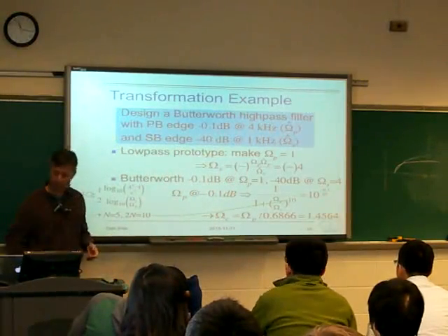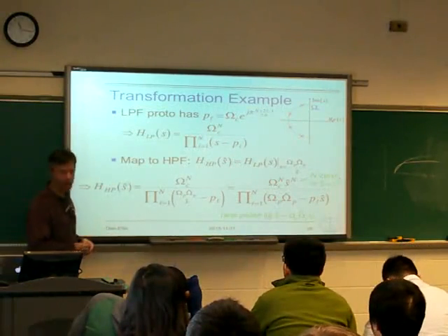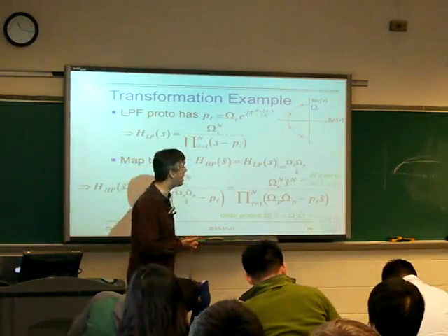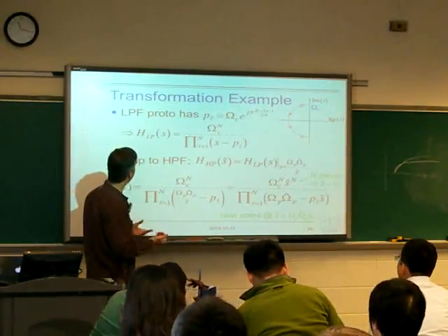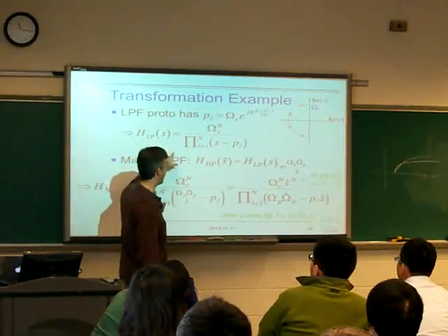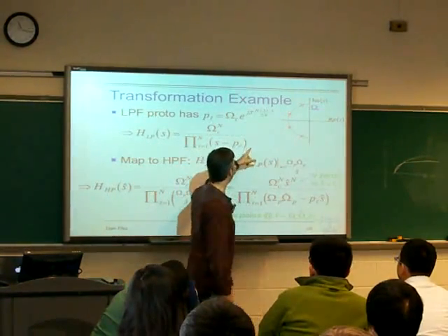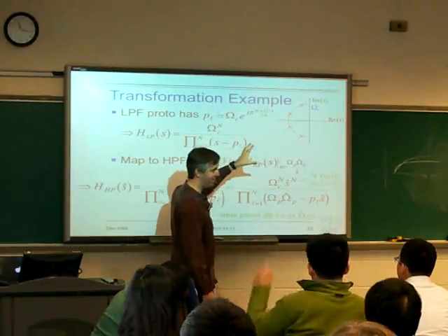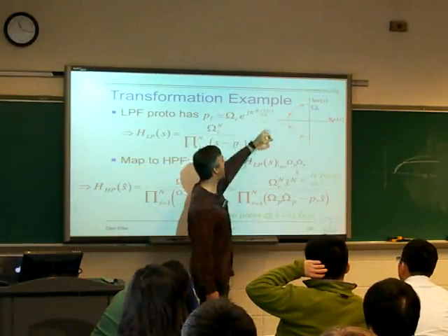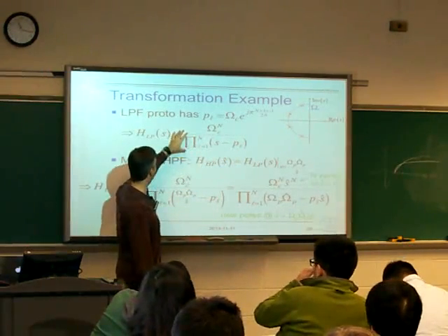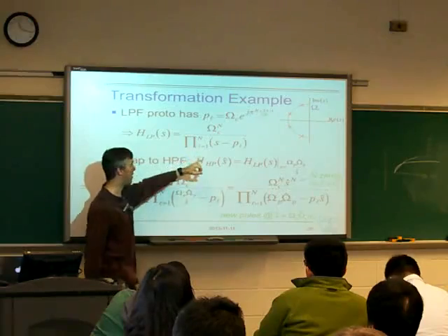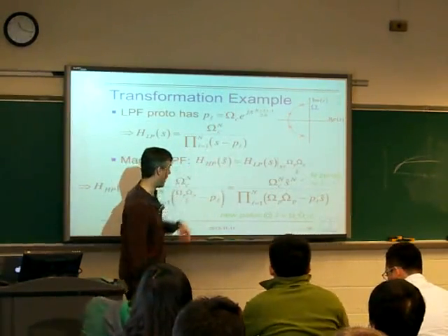And then we can get our low-pass prototype, we can get our low-pass polynomial out, and we can do the substitution to get the high-pass out. In fact, for Butterworth, we know what the polynomial is. It's a circle with these odd-indexed poles at the radius omega c. Normally you wouldn't have to do that, but it just happens that we know that. Here's a nice little expression to say that. But it's going to show up as a polynomial like this, with a product of a set of roots, these poles, which are those red x's.